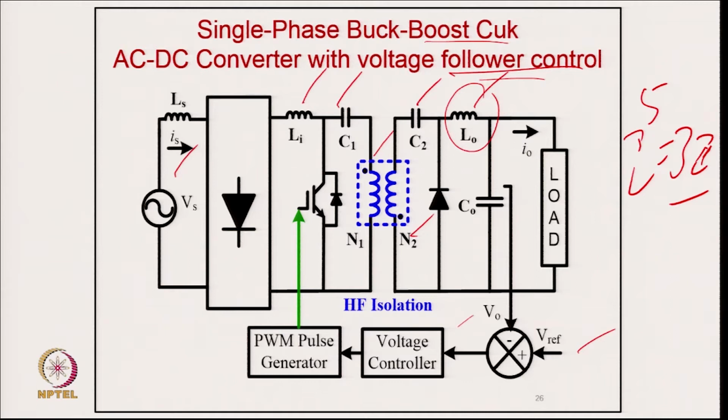That is the reason for nominal cases we design this converter around 0.5 duty cycle, and the voltage ratio for which we are designing, we can take with the help of the transformer turns ratio N1 by N2. You can also have multiple secondaries, required for many applications.